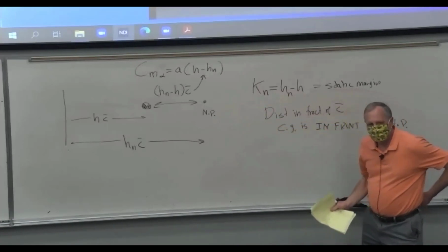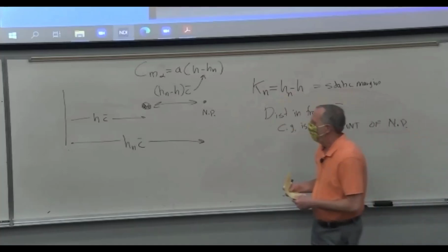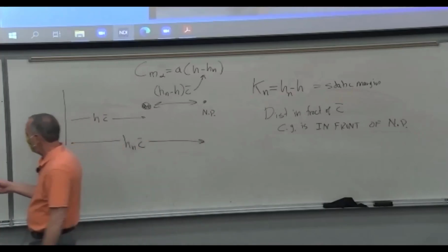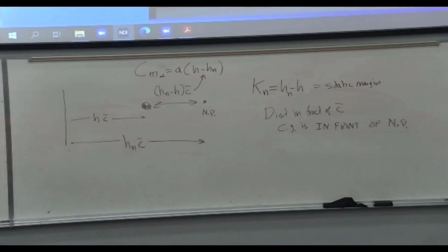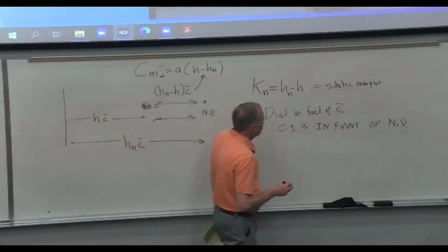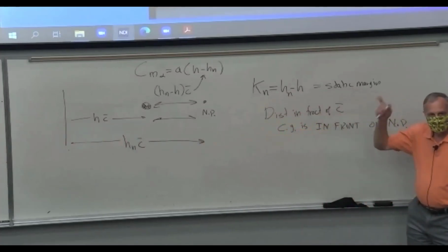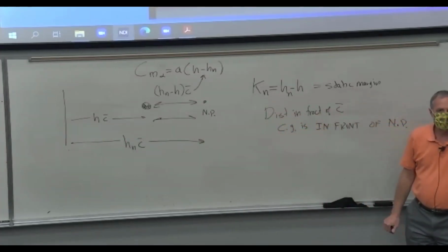And so often people will quote stability for an airplane not as Cm alpha is negative 0.4, because what does that mean on the airplane? There's no physical measurement that's just Cm alpha. But if you say, hey, this distance, the static margin, is 0.1 c bar, then you know where that is on the airplane.